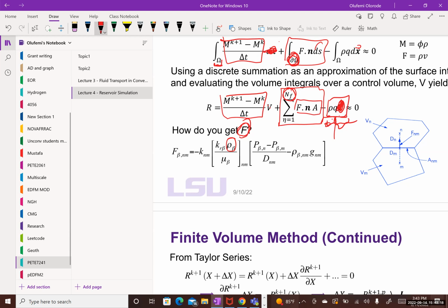If you want some simplistic approximations, you put all of the equations and you're substituting and changing the governing equation, you don't need all of that. You want your code to be generic. If it's for gas, go in there and in your compute density function, then use PM over ZRT. And then you go create a function that will compute Z from the equation of state.